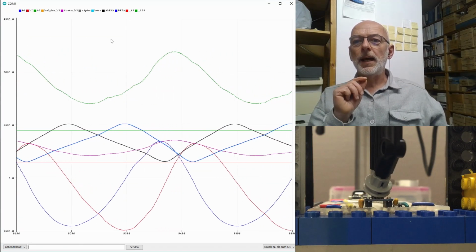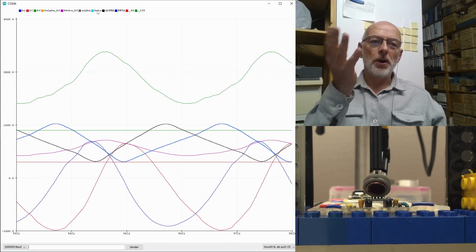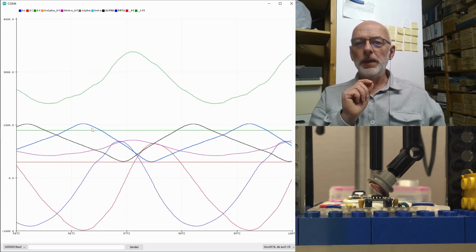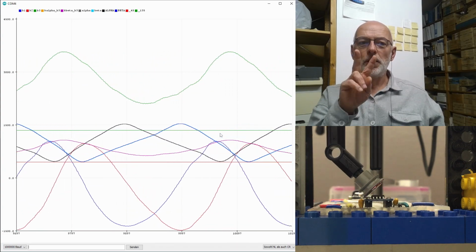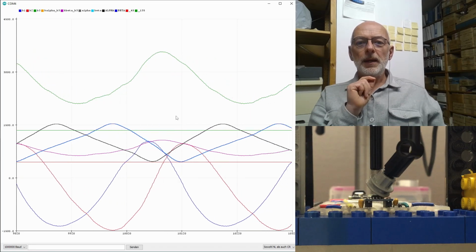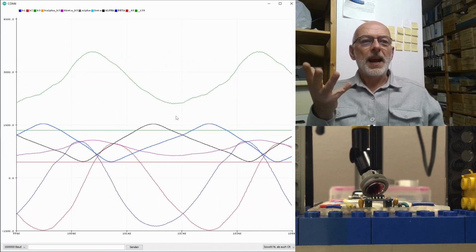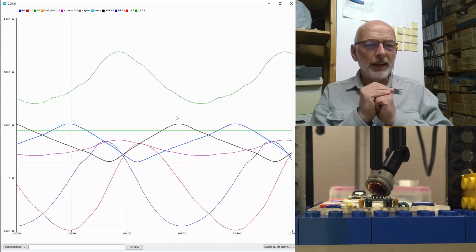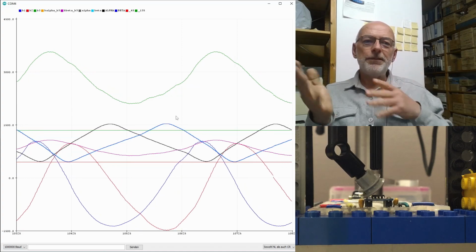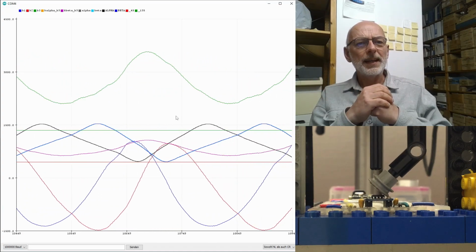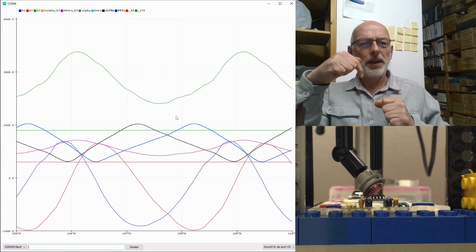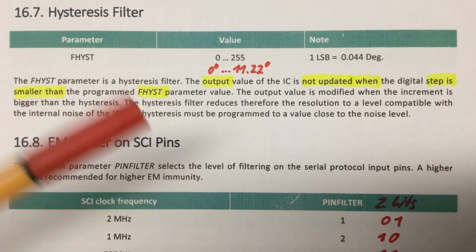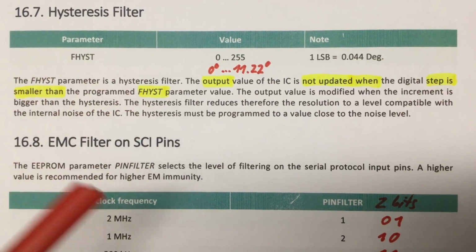And indeed, the alpha and beta angle returned from the chip still overlap with the alpha and beta angle we calculate. As we can see, there are no two curves, they are overlapping. Perfect. So at least there, even if it doesn't make sense from my perspective, the datasheet is correct for once. If you have any idea what you can actually do with that KT parameter, let me know in the comments. That was 3D and it works as described in the datasheet, which is good.